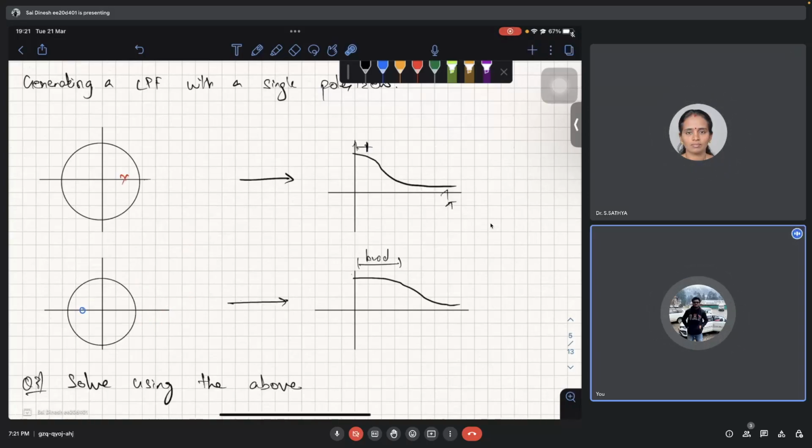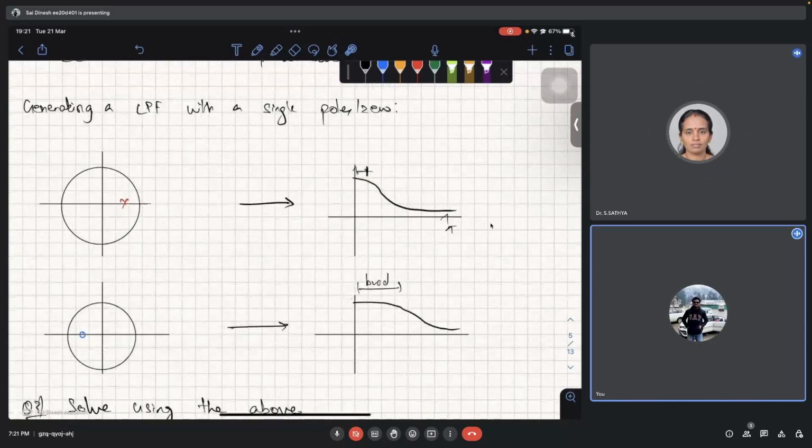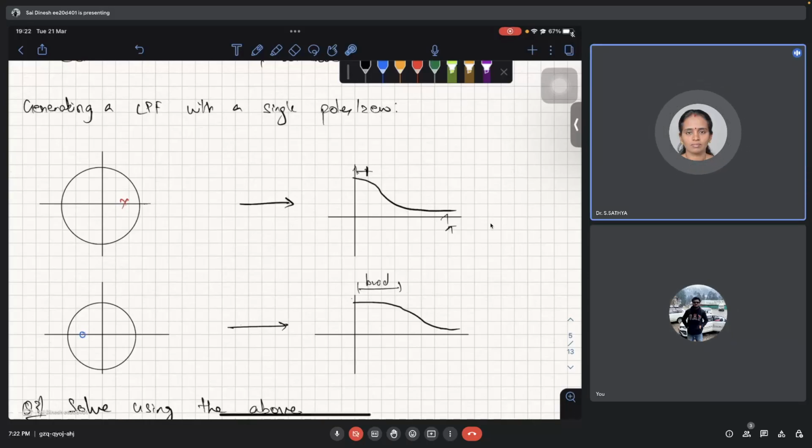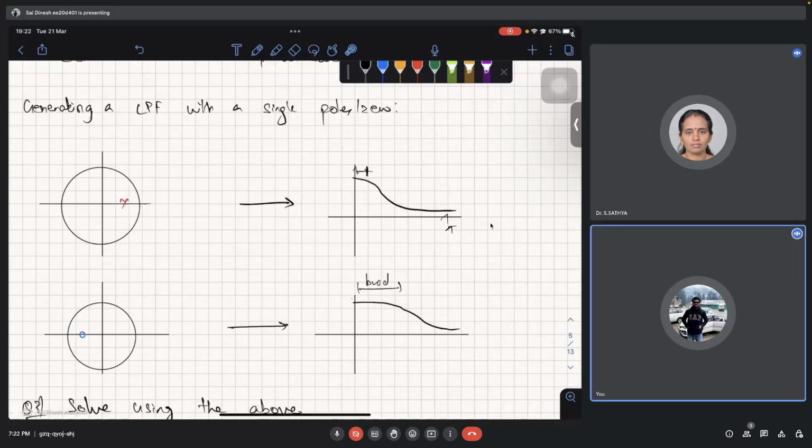So that is where the pole zero plots come in, and you also talk about the stability of systems, how the inverse of a system works, and then minimum phase systems, right? You say that if all poles and zeros are inside the unit circle, it will be a stable system. Yes, all these concepts matter when the actual filters are designed.